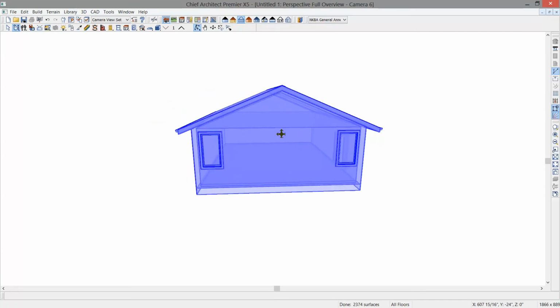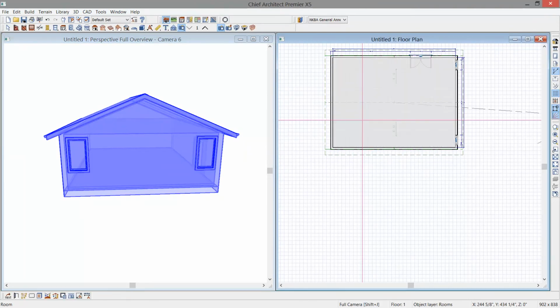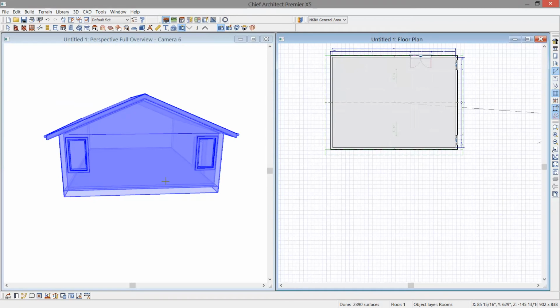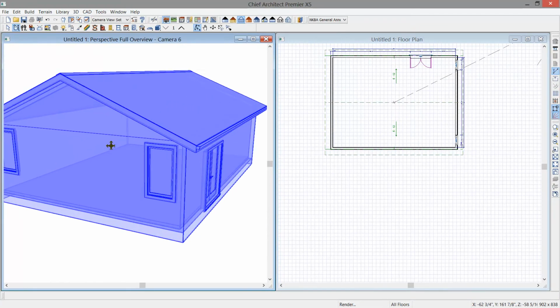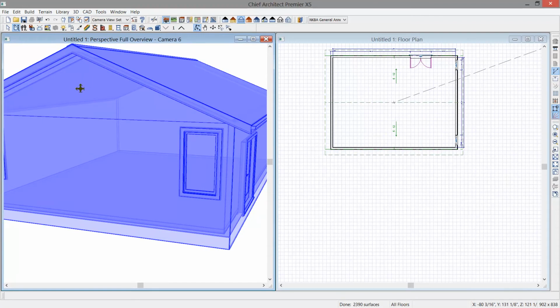And you'll notice in this glasshouse view that I still have a ceiling plane in there. So what I will do is click on the room here, and let's go ahead and remove that ceiling out of there because I want it to be a vaulted open area in the kitchen and living space. We'll regenerate that view and get rid of the ceiling, and you're actually just seeing the attic line in there, but the ceiling plane is now out. So I have an envelope here that we can go ahead and generate our truss in.